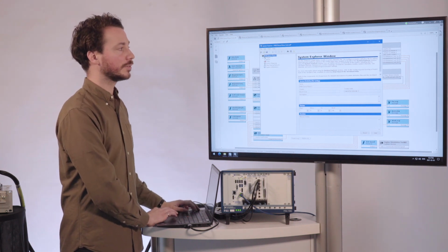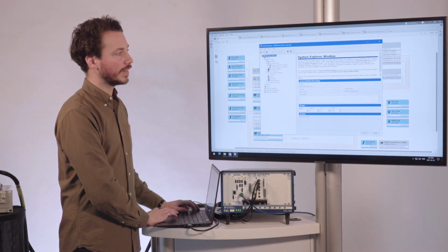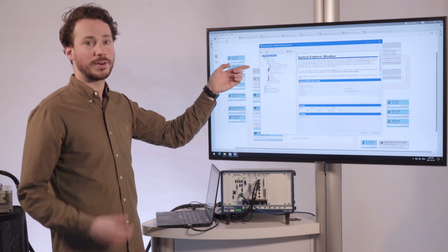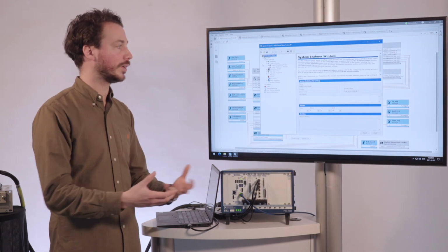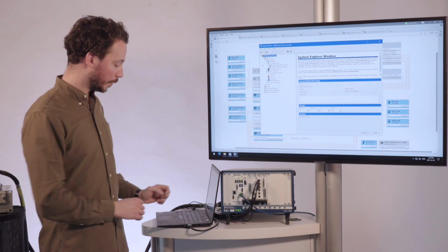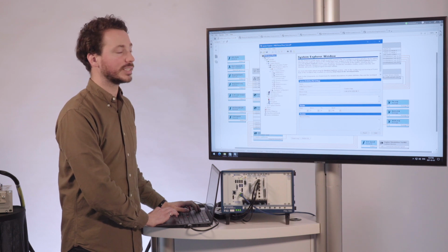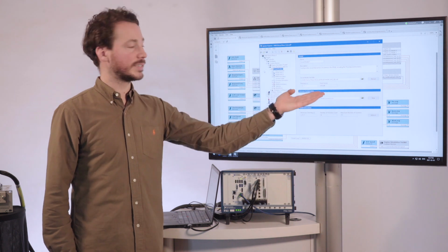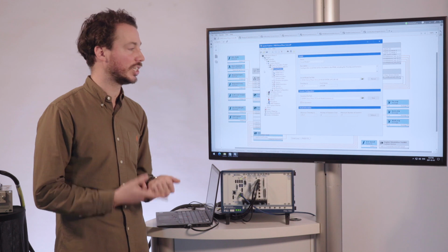As I expand my left-hand tree here, we can see that under custom devices, there are two custom devices. The first one is the engine simulation toolkit from NI. So that's meant to simulate the engine. You can take real engine data, import it, send it as an analog channel, etc. It's a very robust tool. And what OPAL-RT specifically designs is the power electronics add-on. So in the power electronics add-on, we have the ability here to create a circuit, in this case based in SimScape, that will simulate the inverter, the boost, the machine, etc.